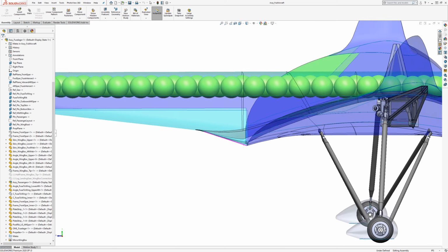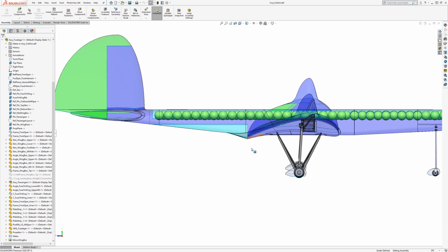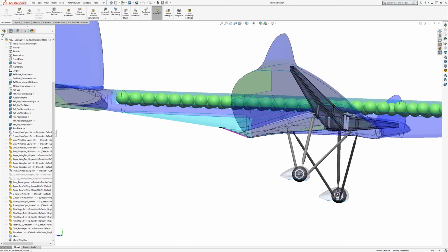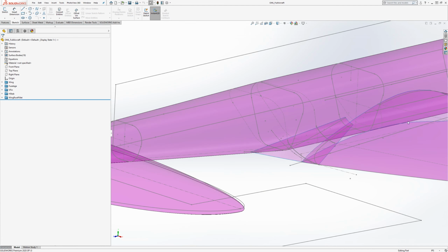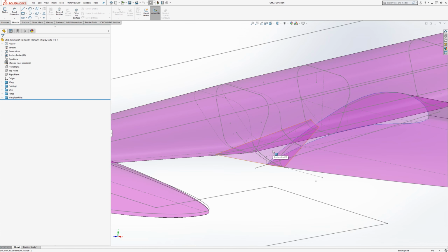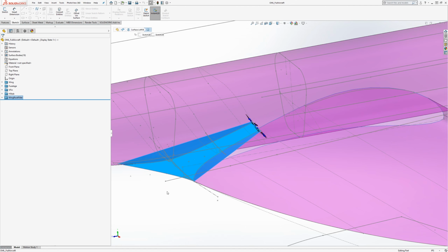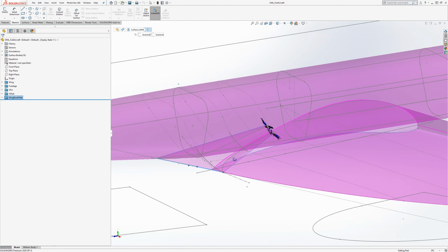so underneath I just filled in all that space, and I would imagine this wouldn't be as good because the airflow comes in and makes an abrupt change in angle underneath the fuselage. So all this one is, in the segments of OML, is a loft just from one arc to another, a double tangent arc, and nothing underneath.